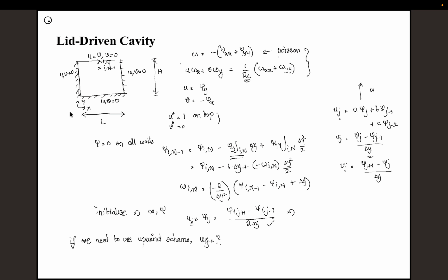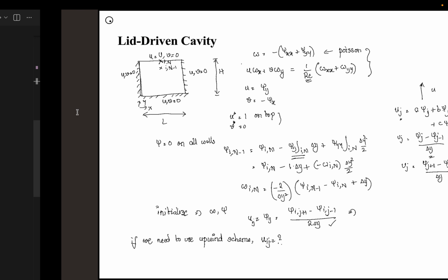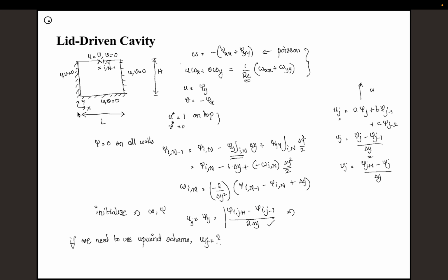We discussed how to do this automatically by using the modulus last week itself, so I don't want to go into all of that. For now, we'll restrict to a very low Reynolds number, so we can simply use this equation. This is basically called central differencing. With central differencing, we can go ahead, and I'll get this u.